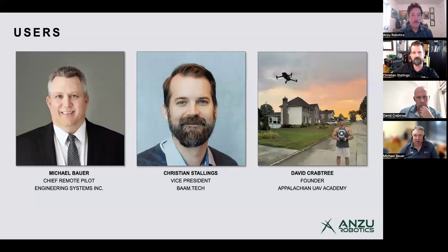We've noticed that while the imagery has been great, it seems to be on par with the M3E, which is what I expected. Pix4D doesn't process it. It doesn't get the gimbal pitch, roll and yaw. It doesn't read it from the EXIF data. It seems to be in the EXIF data because I investigated all this. So I've been talking with Aloft and Pix4D to see how to make that connection. I do have a workaround that brings it in, and I've been successful in all my maps and processed data that I get out of Pix4D.